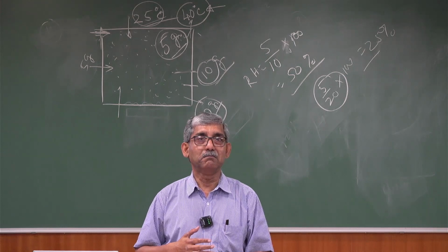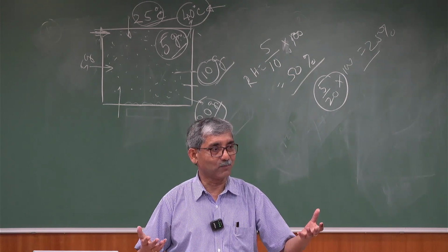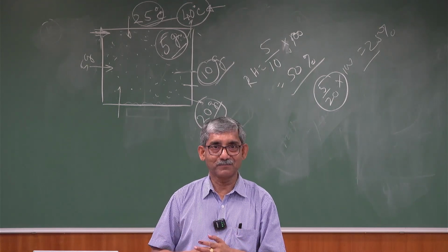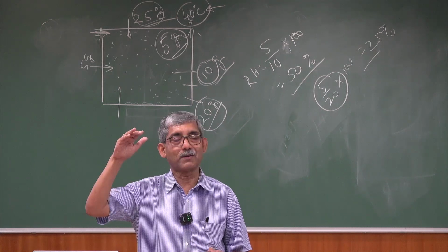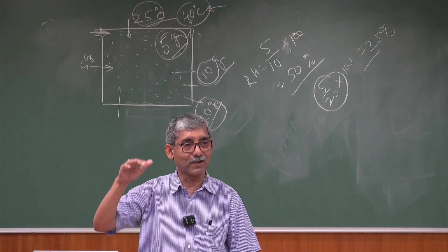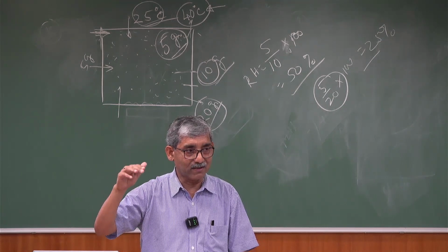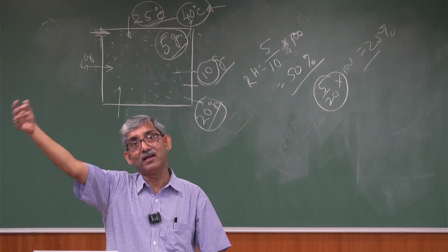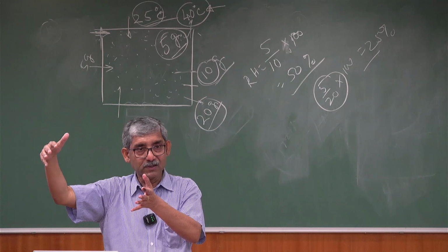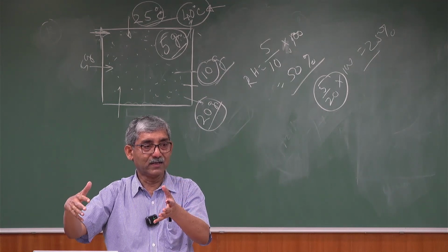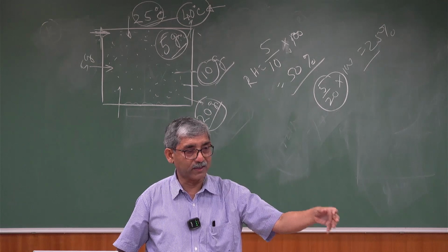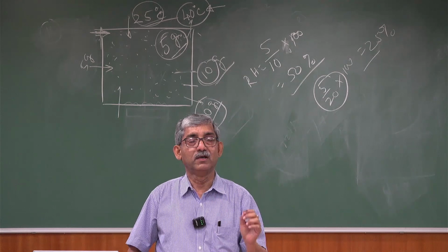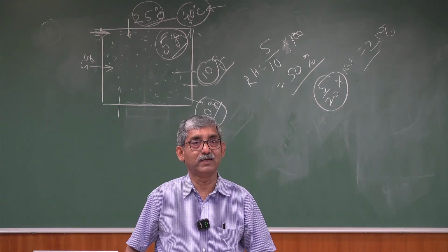But we cannot always achieve the ideal condition. There will be some deviation, the machine will have some deviation, and that deviation is expressed in terms of index of irregularity, the ratio of actual irregularity and the limit irregularity, which is known as the index of irregularity. That we will discuss with different numericals.